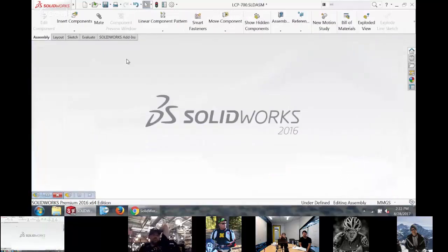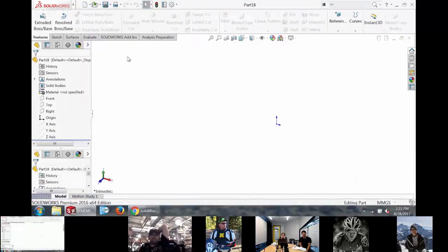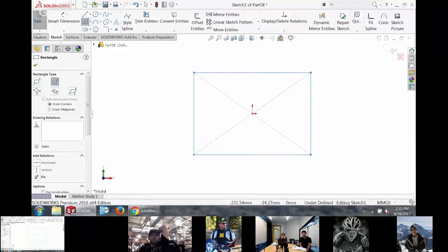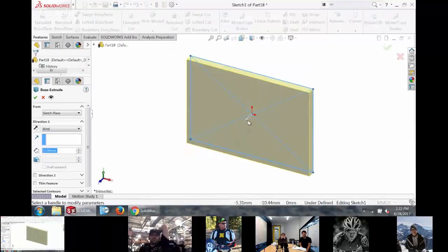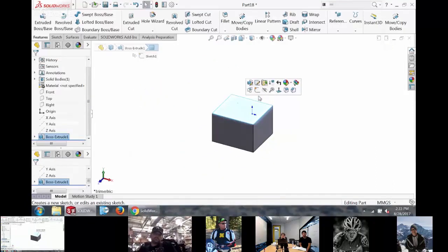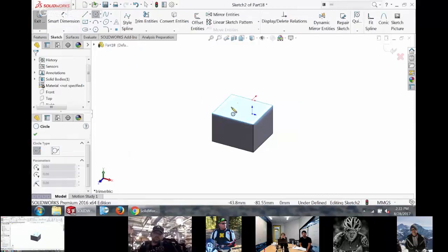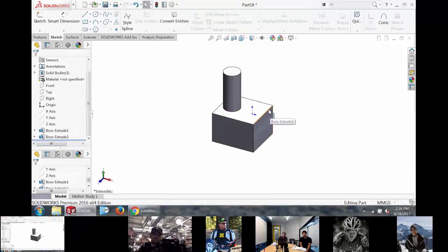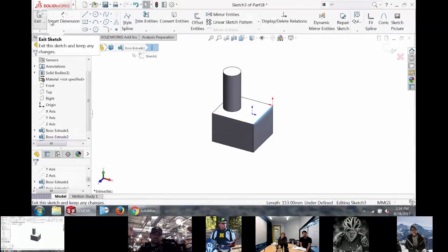I did just want to do a few of them that are basic mistakes that people make all the time, how to avoid them, or how to know what happened. One of them is opening a sketch on an edge. So typically when you're sketching, if you pick a face and you start a sketch, of course that sketch will be on that face. The thing that gets people in trouble is they think they picked a face, but they picked an edge.